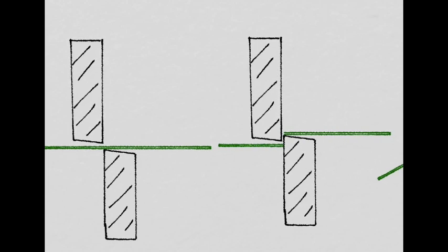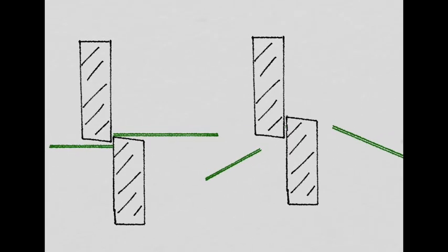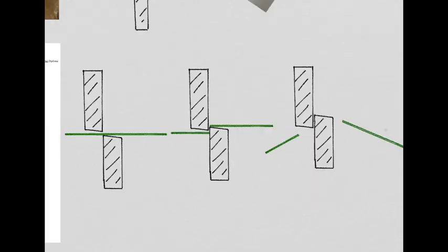Now I use the word cut, but in fact we should say sheared the piece of paper, because that's exactly what's happened to the piece of paper. It's a right hand half. This half here has been pressed upwards, and the left hand half has been pressed downwards, and there the failure occurred. And in fact the piece of paper did not get cut. The piece of paper failed in shear, and there the pieces of paper fall to the ground and the two blades pass by each other, their work having been completed. So that is the concept of shear and shear force, and in this case shear failure as well.